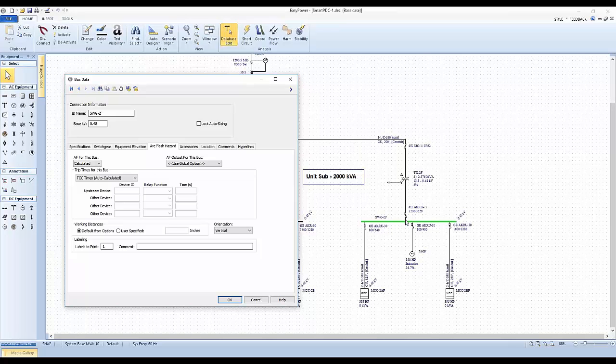So if we initiate a fault by dropping a wrench, let's say, across a couple of phases as I'm working on the hot switchgear, and that plasma ball encompasses this main breaker, it could arc itself at the bare conductors above the breaker. So in that case, the arc flash output for this bus would have to exclude the main in terms of calculations.